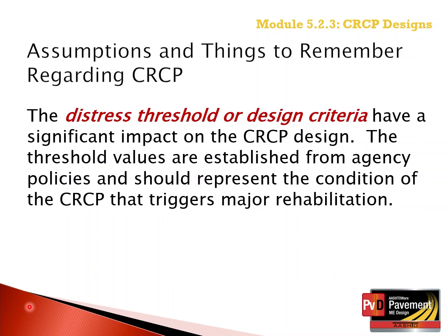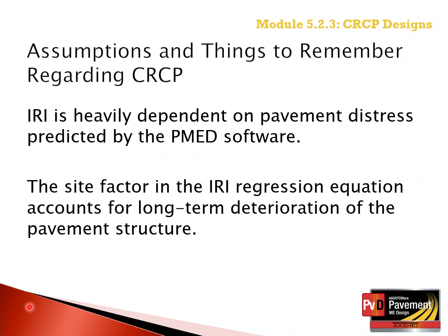Remember, the distress threshold values and/or design criteria need to represent the agency's policy of when to rehabilitate or repair the pavement. So these values represent the surface condition that triggers major rehabilitation. The fundamental performance of the pavement is estimated through the calculation of IRI throughout the design life.